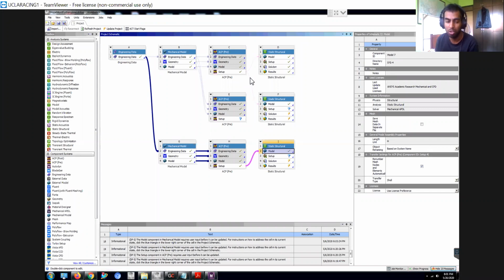Coming up with the constraints is up to you as a designer. The constraints mainly focus on things to do with the driver. It has to be really stiff, so deformation has to be less than an inch. Things like the steering wheel should definitely be super stiff, less than a millimeter of deformation at max loading.